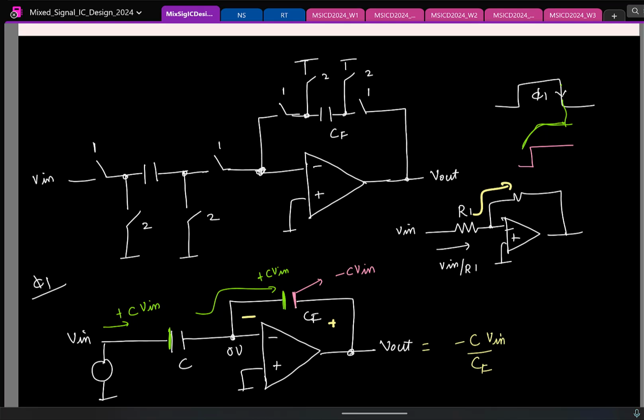So are we still sure that this new circuit will compensate the channel charge? Okay, again same thing, right? If this is the case, channel charge is problematic from this switch. So what if you do bottom plate sampling as usual, what switch do you turn off first? I mean, input is sampled like this, so you make sure this is turned off. Same thing, right? Whenever you have a switch connected to the input, you will have signal dependent charge injection. The solution is bottom plate sampling. We have the other switch and turn that off a bit earlier.